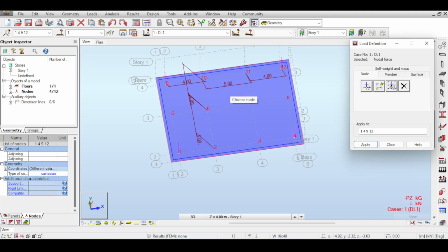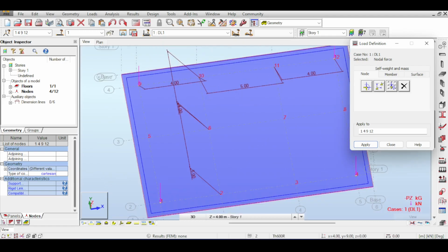Okay, fantastic. Now going on, the tributary area is 4 and 2.5 is 4.5 multiplied by 2. 4.5 multiplied by 2 is 9 meters square. I'm doing a very quick in-head calculation. I'm not using a calculator, to be honest. So pardon me if there is a small mathematical mistake. Anyway, the area here is 9 meters square. This is for each story. The dead load per one story is 9 multiplied by 10, which is 90. And the live load per story is 9 multiplied by 4, which is 36.